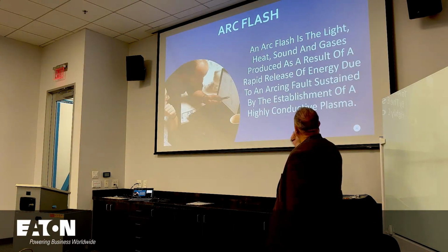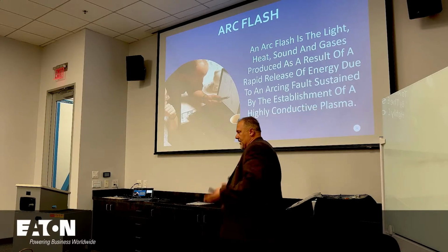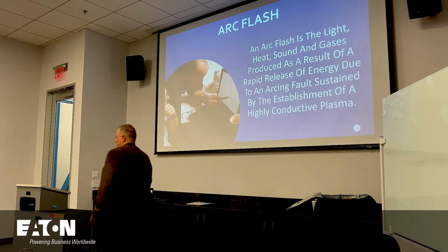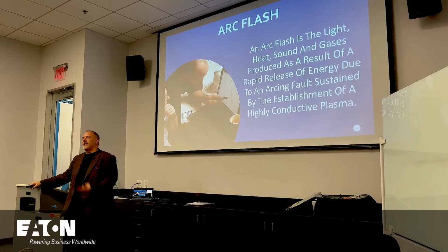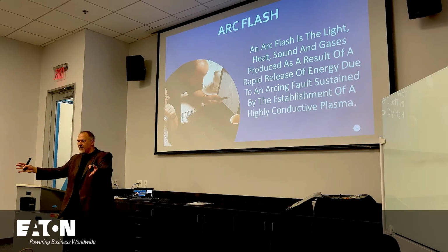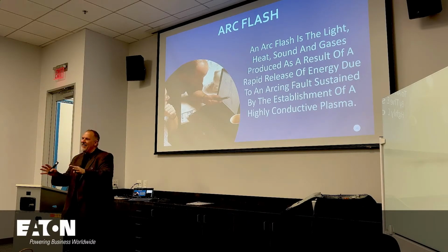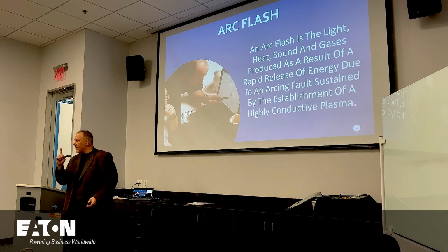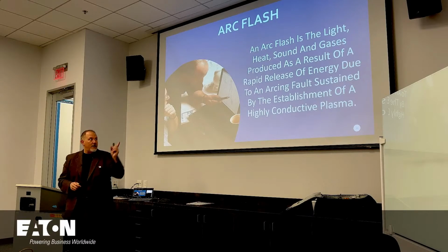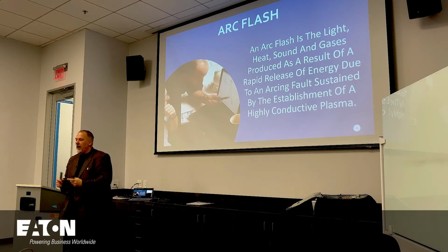Arc flash. An arc flash is the light, heat, sound. So if you think about an arc flash event, unfortunately, whenever we talk 70E, everybody wants to talk about arc flash. Why? Because we have the rubberneck syndrome, right? We want to all watch the big lights go off and all the events. More people die from shock. More people die from shock. But arc flash, and we have shock protection in the National Electrical Code. We have barrier requirements, all that other great stuff. So I do want to say, although we're going to talk about incident energy, shock is the number one killer out there for us. But when an arc flash event goes off, you have light, heat, sound.